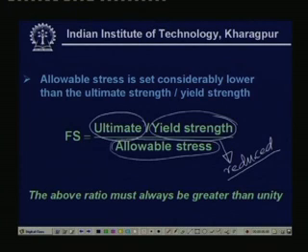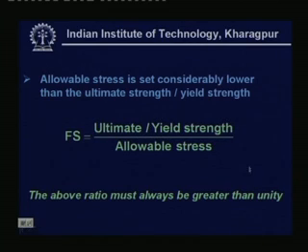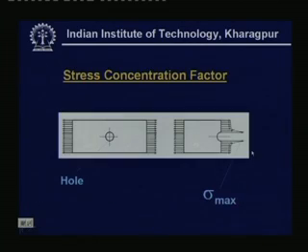Suppose a case like welding etc., takes quite a good amount of factor of safety, whereas simple structural designs for the static load etc., take a design factor of 1.5 or 2 like that. So, really this factor of safety depends upon the type of design you are interested in. Now, once we know this particular factor of safety, then we go to another idea that is called the stress concentration factor.